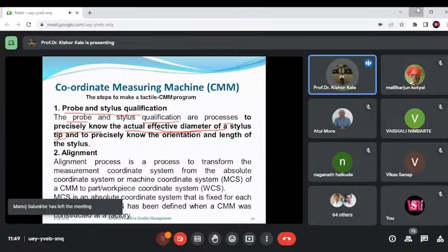For models without datum planes, localization is done in 2 steps: initial pose estimation and solution refinement. That means without datum planes, because in some cases the datums are very different, the correspondence can still be done. In the approximate solution, distance is minimized between the CAD model and point data by using the least mean square distance, considering the entire CAD model and point cloud. So the distance between the 2 points should be minimized.